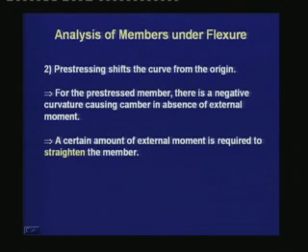A certain amount of external moment is required to straighten the member. That means we need some external load to have zero curvature in a prestressed member, whereas in a reinforced concrete member the curvature is zero in absence of any external load.